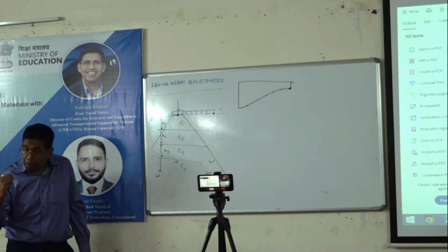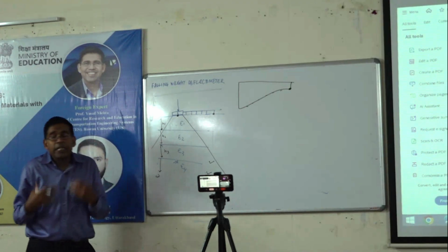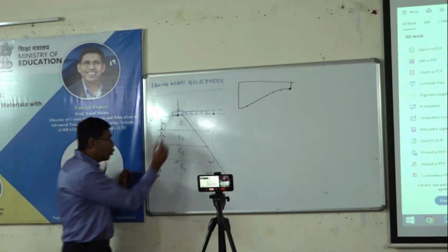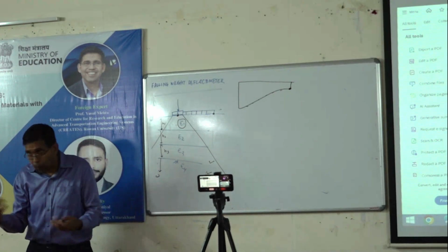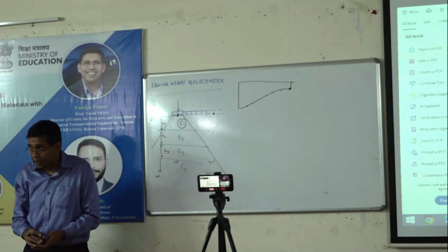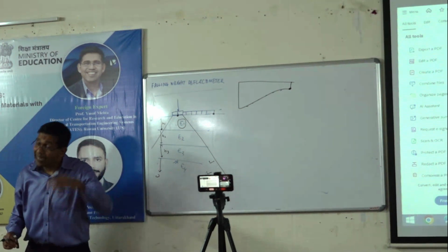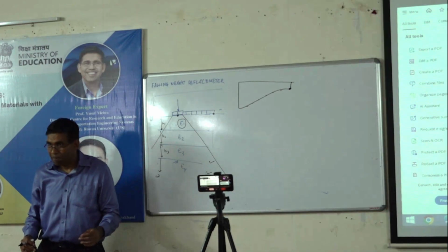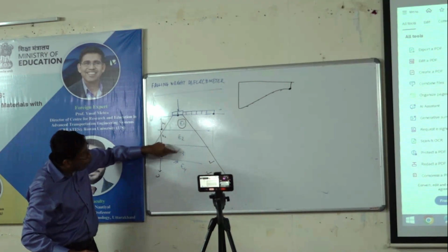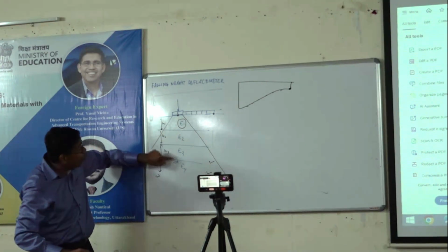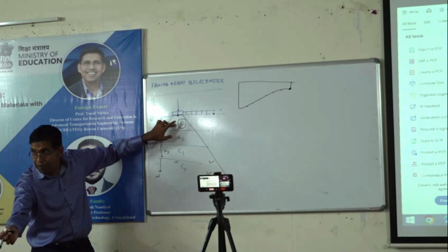So when I do FWD testing, 99% my goal is to get the property of the top layer. That's the one that's failed, right? That's the one I want to replace, all right? Does that make sense? However, unfortunately in FWD, that is the least confidence I have, because this deflection is happening to all 4 layers. If I don't know the confidence of these 4 layers, any of these numbers, my confidence in E1 drops. Can everybody understand that?